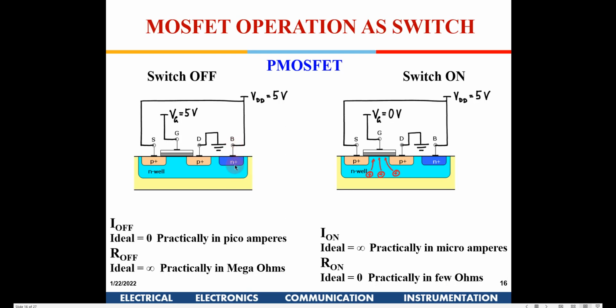When you highly dope it, the Fermi level becomes close to that of a metal. Although a sharp boundary is shown here, when we actually dope it, there will be a gradual transition from N to N plus to the metal, so that there are no additional potential barriers formed.